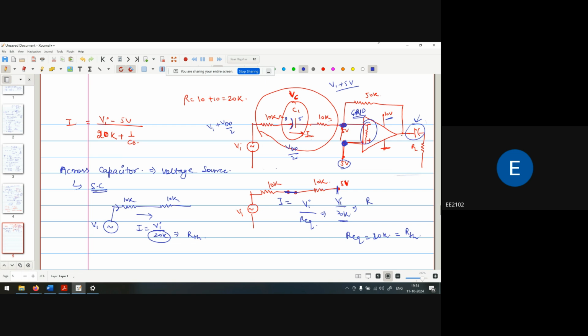Okay, so if we short this capacitor from this point to this particular path, only 1 kilo ohm resistance is available. So it is the R equivalent for C2, or RTH for C2. Again, if the circuit is not completed, how can we say that this is the RTH?